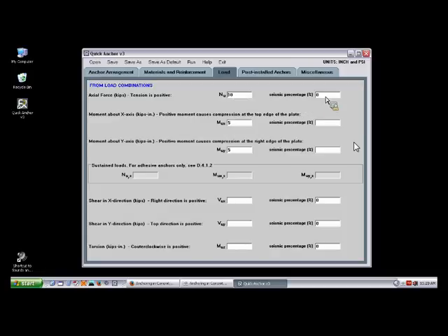And then we have these boxes that say seismic percentage. Now this is only relevant if you are using ACI 318-11, as most of you are probably doing anyway. ACI 318 Appendix D has certain special requirements that apply only when you have seismic loading on the anchors. Now in ACI 318-05 and 318-08, those requirements kicked in if the seismic design category of your building was C or higher. That was the only criterion. But now, starting with ACI 318-11 and also in ACI 318-14, we have a separate threshold for these seismic requirements to kick in.